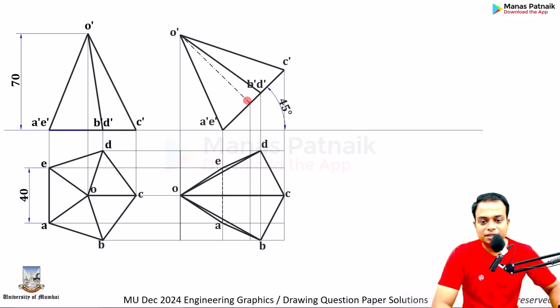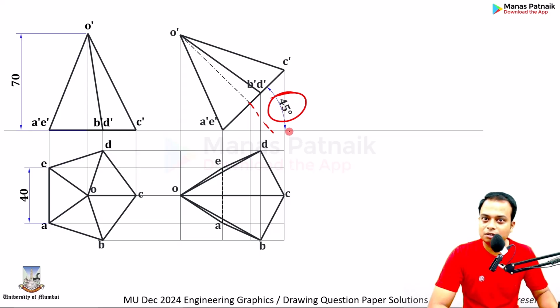So basically here, I made a small mistake. I don't know if you guys realized it or not. Whatever data has been given in the question should reflect in your drawing. In fact, there is no data of the base given. Okay, this was my inference. Instead of writing this dimension, I should have written this. Yes, I fixed the base at an angle of 45 degree, but that 45 degree shouldn't have been mentioned. This 45 degree that the axis makes with respect to the HP should have been mentioned, and you guys do that. Okay. Now, in step number 3, this is going to be very simple.